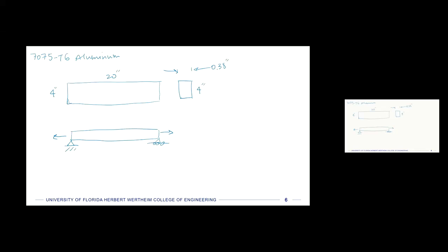Okay, so through the thickness crack, right? So it extends all the way through the 0.38 inches. What does it say? Single edge through the thickness crack. So it goes all the way through the thickness, and I'm just going to draw a crack here so we can use that as our example. So the a of that crack is 0.15 inches, and it goes all the way through the thickness. So if we look at an end-on view, yeah, it goes all the way back through there, all the way through the thickness off of one edge.